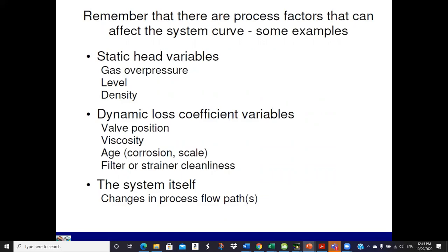Density: if these are tanks that are outside in the environment in the summertime, that stuff may tend to be warm, with the sun beating on it all the time. And in the wintertime, you get an old northern blow through and it's -5 degrees. Depending on what the fluid is, you may have to heat it to keep it from freezing. So you will have density changes over the course of some period of time.